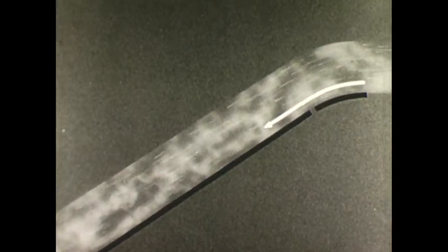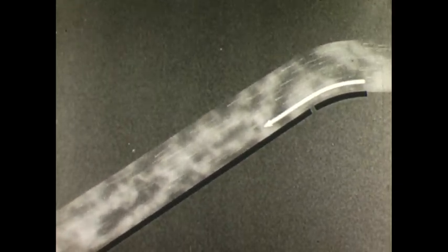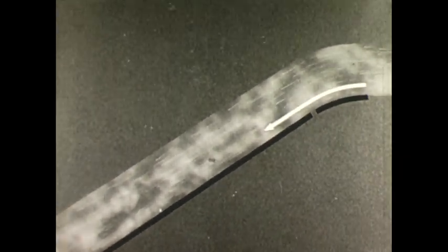By adding a curved approach to the leading edge, abrupt change of direction is prevented. The airstream nearest the leading edge remains in contact with the surface, and a more orderly flow takes place. The actual airstream verifies our conclusion as to the effect of the curved leading edge. Although some turbulence still exists, the airflow over this cambered plate is smooth up to the higher angles of attack.